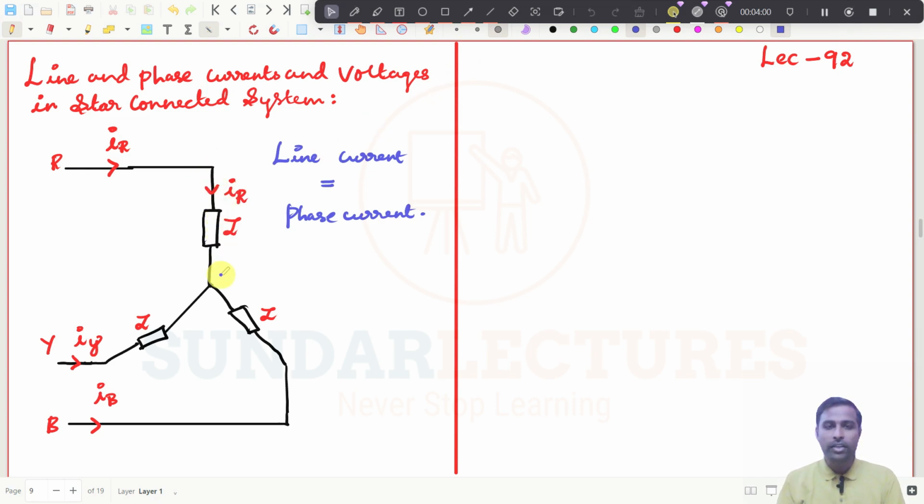What is the voltage coming through this load? That is nothing but, we will call it RY, right? From here to this point, we generally call this point the neutral. And for phase voltages, whatever is connected between neutral and the wire here, it is the voltage through this particular impedance, which means the phase voltages. We will call it VR up to this point, and up to this point it is VY, and up to this point it is VB.